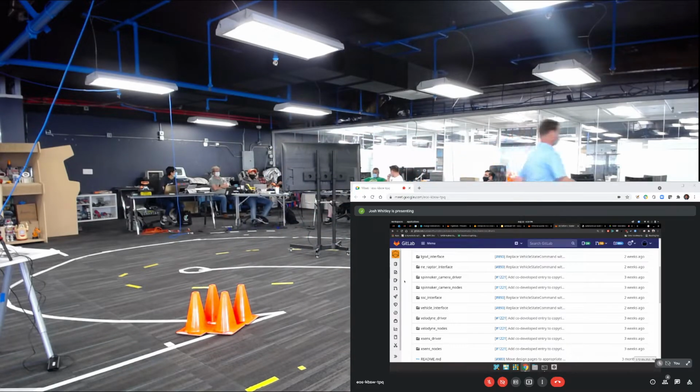And then can I install it, or should I then just get the source to here or what? So for Autoware, we currently don't release any of our packages onto the ROS repo, so they're not available as apt installs. Yes, that's what I meant. So it is like the F1 template. The vehicle interface part would go in here, and it won't be released on the ROS build farm. It'll just be in Autoware.Auto. But the VESC driver will be released on the build farm because that is totally unassociated with Autoware.Auto.